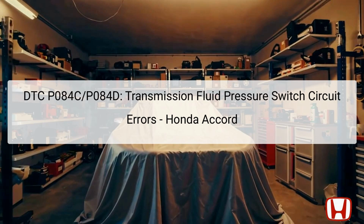The transmission fluid pressure switch is crucial for monitoring hydraulic pressure within the automatic transmission, impacting shifting performance and overall vehicle responsiveness. When these codes are thrown, it suggests a malfunction in the switch, circuit, or potentially the transmission control module, TCM. Proper diagnosis is crucial as this can affect vehicle drivability and reliability. We will explore the definition, potential causes, symptoms, and a detailed step-by-step troubleshooting guide for these fault codes.